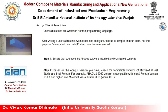When we are doing a heat transfer calculation, the DFLUX subroutine is needed. When we are doing a welding analysis, we need the DFLUX and user subroutines. Right now in ANSYS it's automatically updated in the newer version, but here I think we have to write the subroutine. Sometimes it is there, but not that accurate.